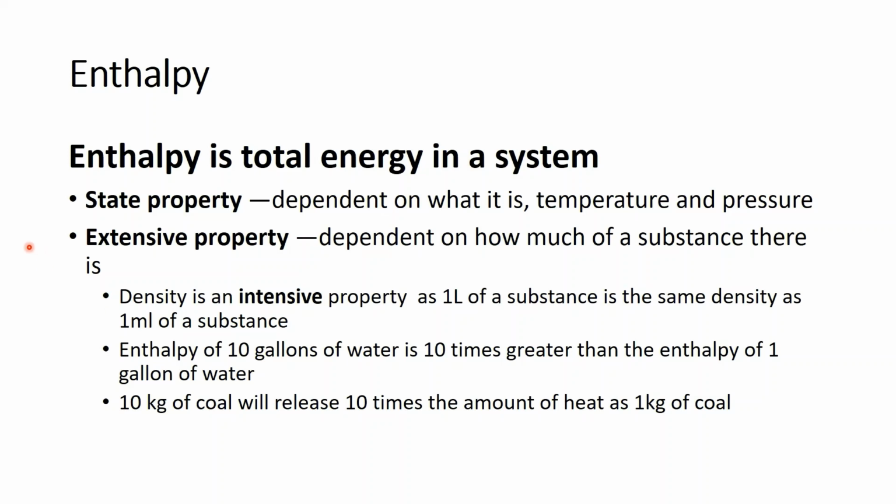Enthalpy, we're going to talk a little bit more about enthalpy, and enthalpy is total energy in the system. It's a state property, so enthalpy depends on what a substance is, what the temperature is, and what the pressure is. I will go ahead and give a spoiler: most of the problems we do here, in fact all of them, I believe, are constant pressure problems. It's an extensive property, so it's dependent on how much of a substance there is. If I have 10 gallons of water, the enthalpy of those 10 gallons is 10 times greater than 1 gallon of water.